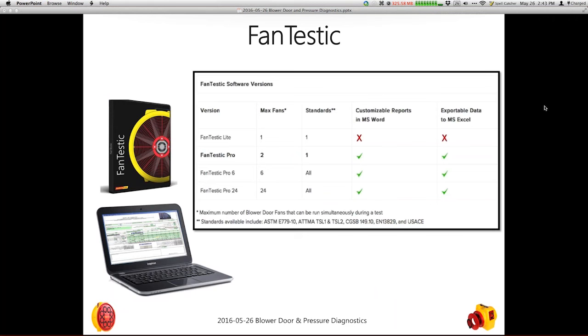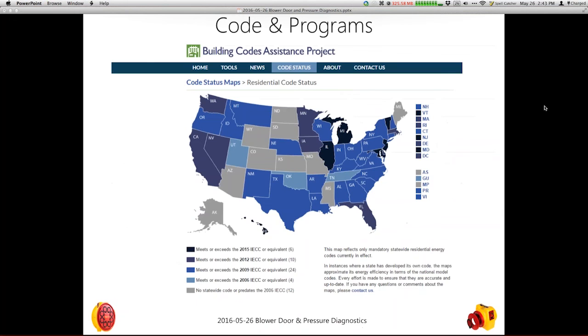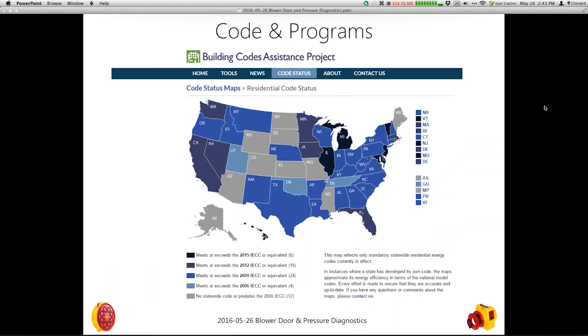What state are you in, or county, and what is your requirement for blower door? Many people have been doing duct testing for a while, but we're trying to get a snapshot on who's doing what for blower door. So let us know what state, since sometimes counties or cities are different, what code you're trying to meet, and what the actual number is that you must comply with. Here in Georgia, we're actually at 7 air changes per hour. Some folks are at 4, some at 5, some at 3. Depending on your construction type, that can be a very challenging number to meet.